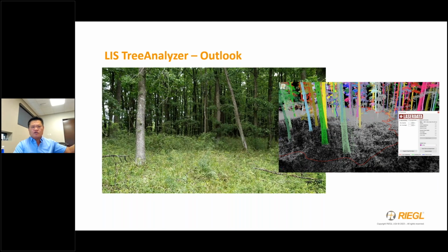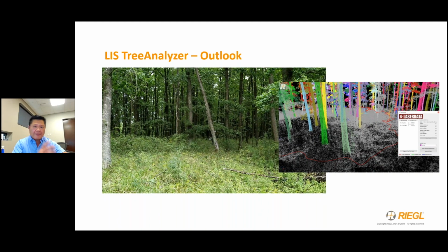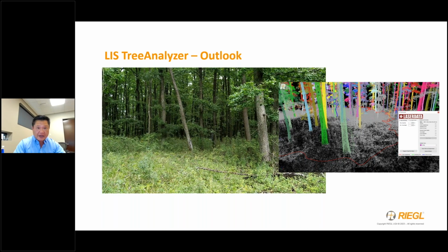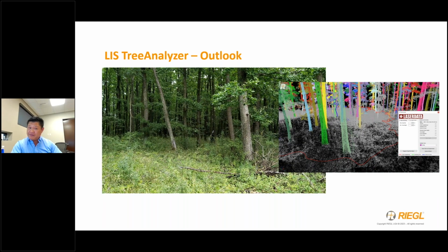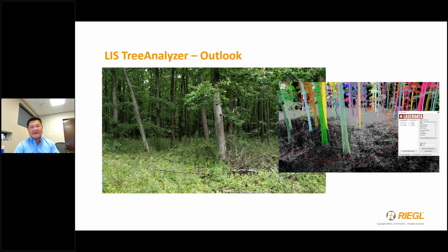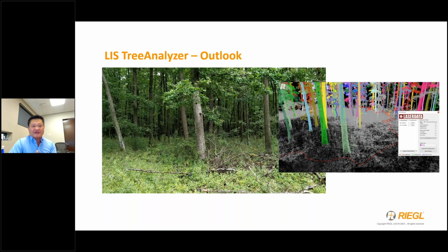I'm not saying go drive down the highway at highway speed, 50 miles per hour or 80 kilometers an hour, and collect data. No, it's not meant for that. It's meant for slow speed, maybe 25 miles per hour or less. And it's RTK, not PPK, maybe we'll implement that later. But yes, we can walk and scan at the same time. Of course, we don't sell the backpack, not that I'm aware of at least, but I think most of us are capable enough to make a backpack and put the scanner on the back. You can't carry it as is, because the thing rotates.